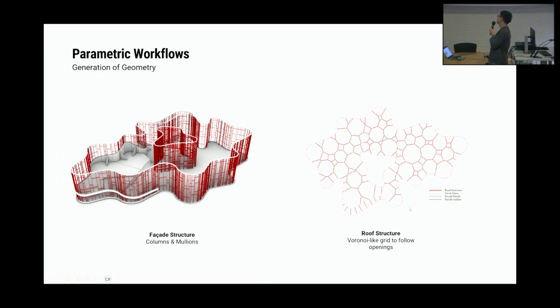So then the facade elements were converted into this 3D geometry. These column positions were set up in the script where, as I mentioned, the rule of 80, 160, or 240 facade width were placed. And then at certain heights, there were vertical mullions that were inserted randomly. The heights of the glass panels were preset at, I think, 2, 4, 6, and 8 meters, maximum 8 meter tall elements. This allowed us to place these mullions, which would also stabilize the columns as well.